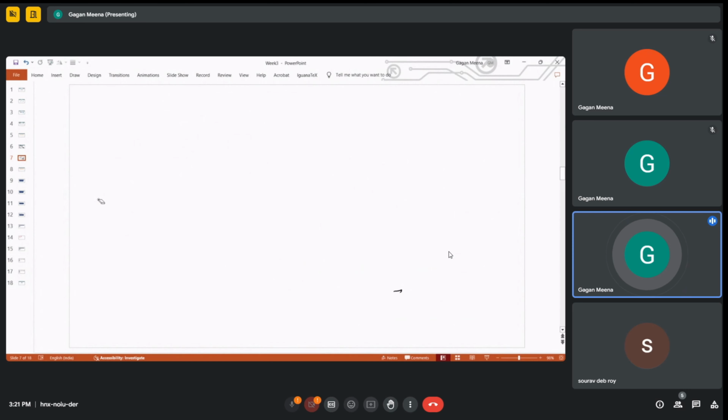So the total loss comes out to be 1 plus lambda 1 into n into I square R AC, which is equal to theta S minus theta A, where theta A is the ambient temperature, divided by the thermal resistance of the protective covering and the soil. So this is the soil and this is the protective covering.